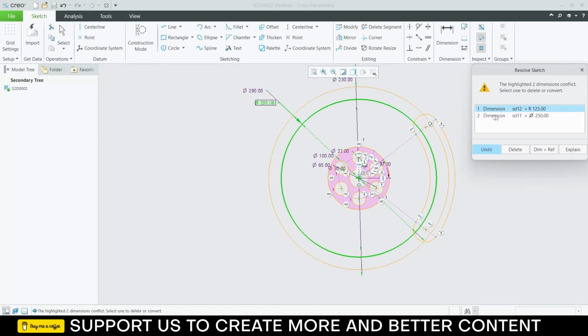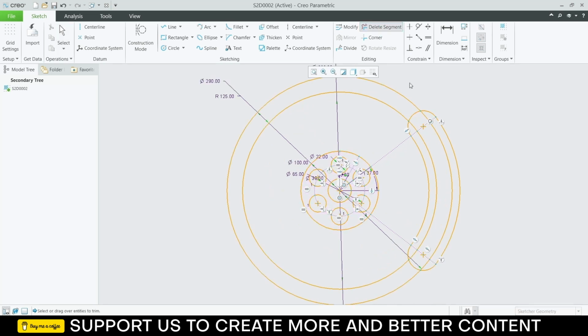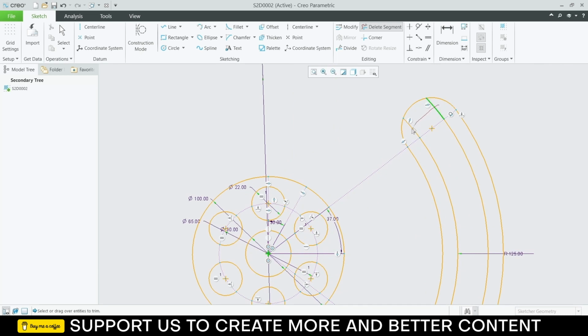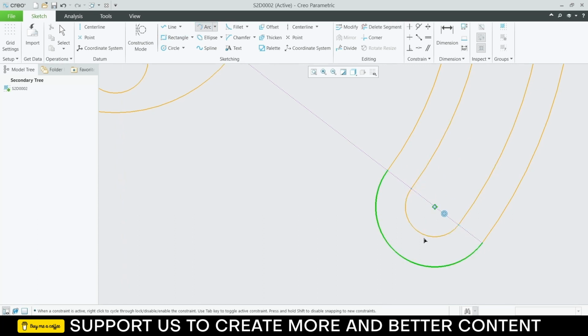So click on here and click on this and delete this, and now you will get the option to enter a radius of 125 mm. It's up to you how you will use it. So click on delete segment and delete these segments. Similarly, delete these segments. Click on arc, select this point and this.